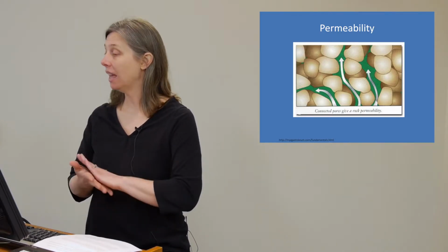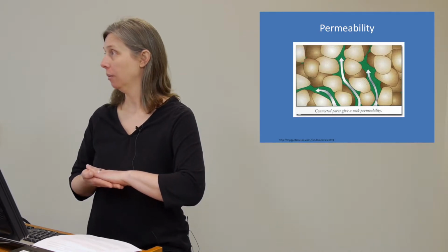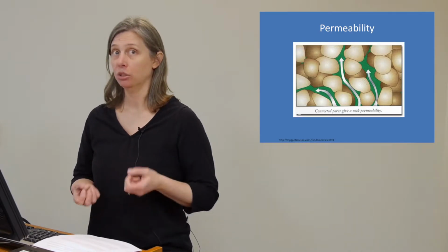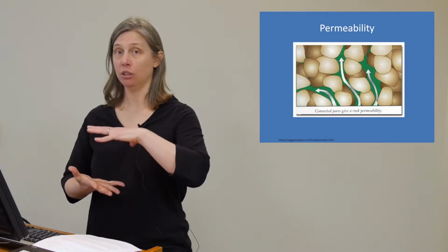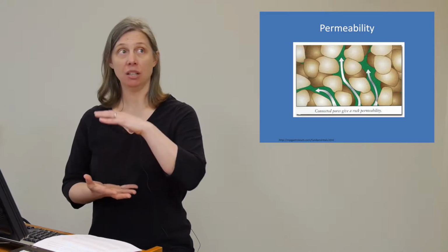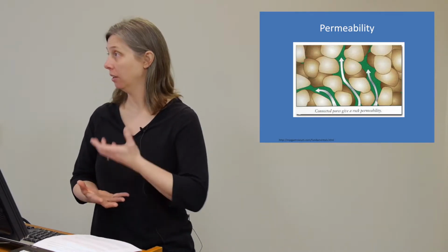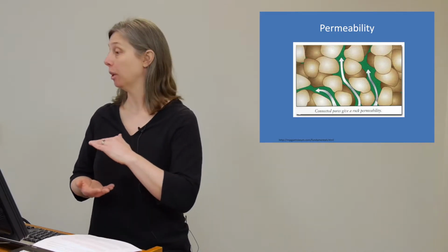So, for instance, clays have low permeability, but they have high porosity. Like a clay in the presence of water tends to swell and can hold a lot of water. So it has very high porosity, but it doesn't allow water to move through those pores, meaning it has very low permeability. So clays often are an impermeable layer, a low hydraulic conductivity layer within our natural geology.